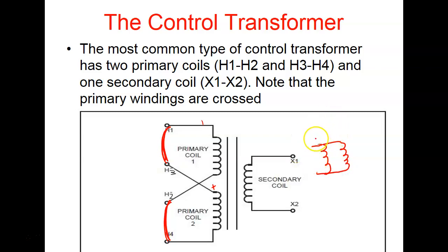So now if I needed 2 amps, then this guy here is going to conduct 1 amp. This guy right here is going to conduct 1 amp, right? So the lower the voltage, the more current we're going to require to put in that primary. So a divide by 2 means what? I'm going to hook them in parallel.